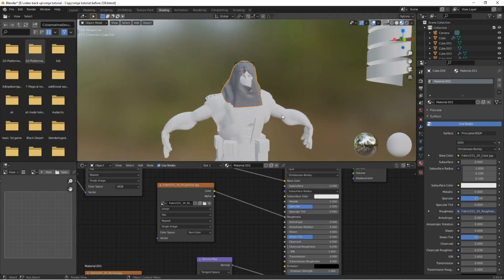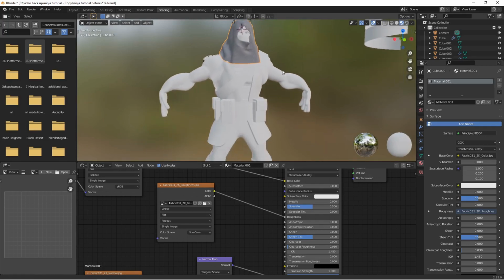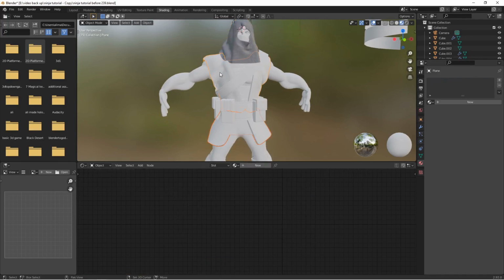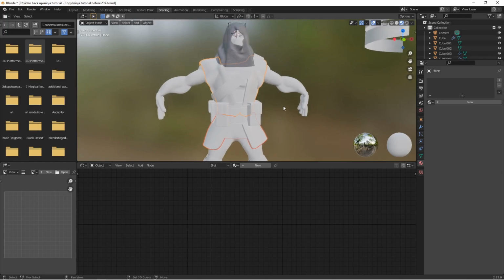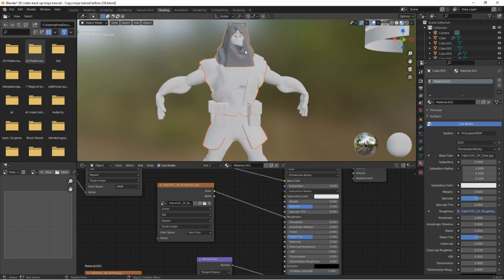All right, with those things set up, what's nice is I want this texture to be on here as well as here, right? So I'll select here, hold Shift, select here, and then while holding Shift, select this. Do I want anything else? Yeah, while holding Shift, I'll select this last. This is the active object because I selected it last. So we have the texture on here, and I want to put that on those other pieces. So I can hold Control, press L. This brings up our Make Links menu, and then I can select Materials. And now those materials are put right onto the other objects, which is very nice. I just left-clicked on nothingness to deselect.